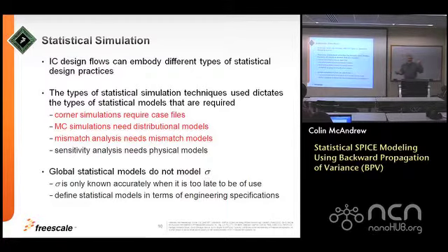So in fact, I many years ago came to the realization that we don't get manufacturing data and generate a sigma from it. What we do is we use that data early on to come up with a specification for the variation for the process, and then we align manufacturing to that window, and we align the models to that window, and then the models will represent the manufacturing process. So that sigma actually comes from engineers understanding what's needed and understanding what's changed in the process. So I will represent it as a sigma, but it's really a specification that then we will treat as plus or minus 3 sigma values.